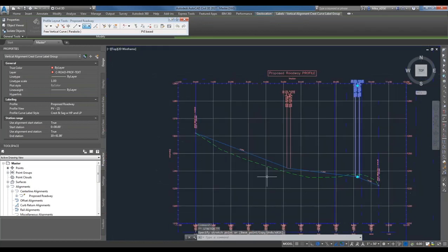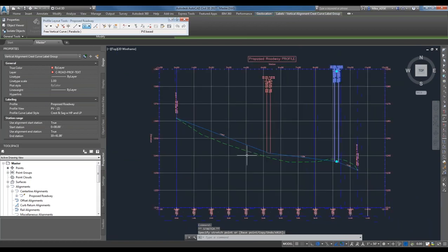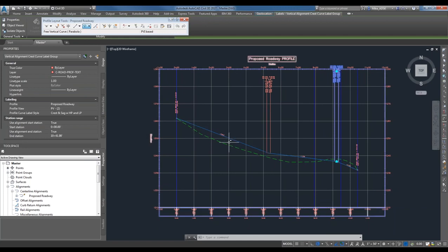So now is probably a good time to start talking about, as you're progressing through your project, the green line was the existing topography. Our blue line is our design. Since we're going so downhill, you could probably imagine that it's going to be a lot of fill in this area. You can't just build your roadway on top of air.